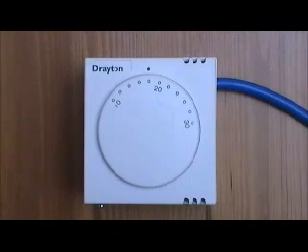Turning a room thermostat to a higher setting will not make the room heat up any faster. How quickly the room heats up depends on the design of the heating system, for example the size of the boiler and the radiators, and the temperature that the boiler is going to increase the water flowing through the radiators to. Neither does the setting affect how quickly the room cools down.